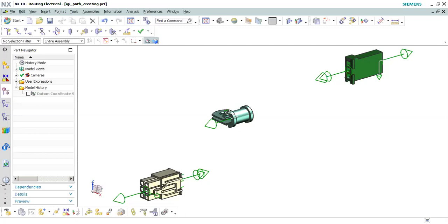The wire harness is usually one of the last components to design because all the components, connectors are used to each application and other components. You need to have a knowledge of the movement or location of other non-electrical components to which you have to route wires through or around. Attachment points for securing the harness must also receive special consideration.